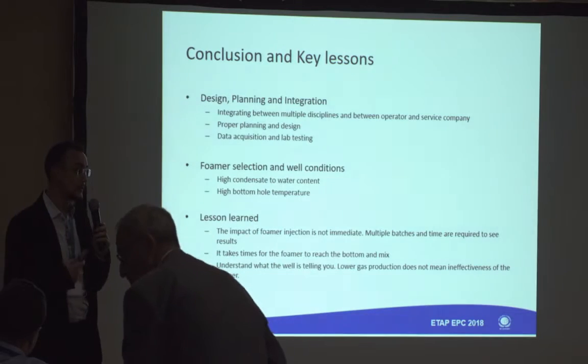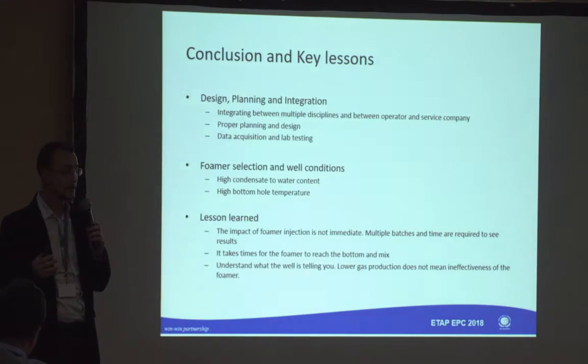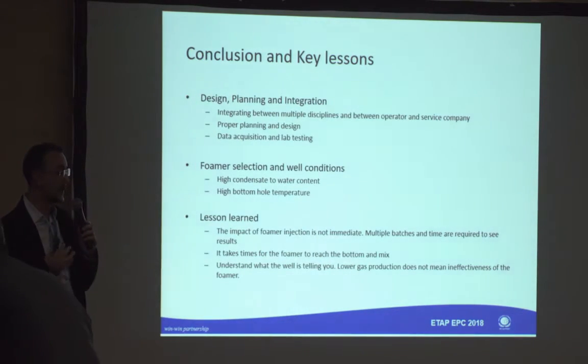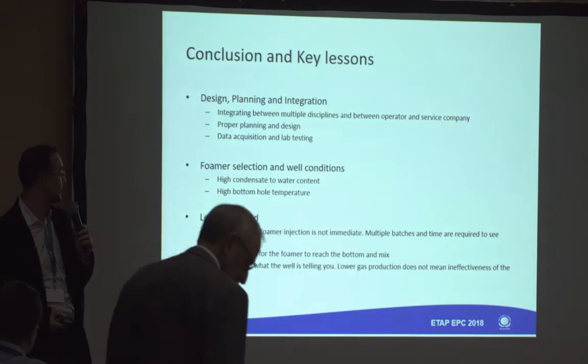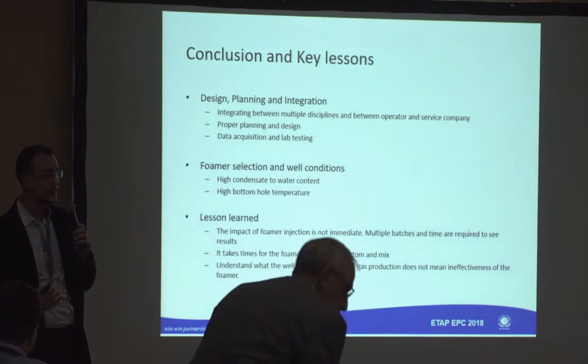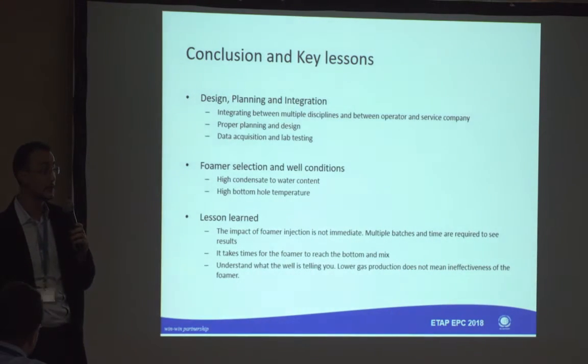So when you do your foamer injection, you have to think that you're not going to just inject and see the results. You have to do multiple batches and take some time to see the impact of the foamer on your production. And it's not necessarily going to improve your gas rate, but it could improve also your uptime, which adds a lot of value as well.